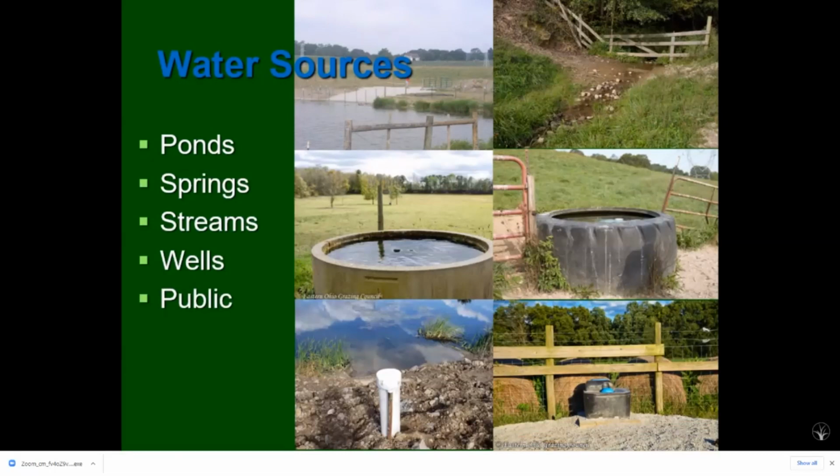Now we're going to get into water sources. And I'm going to spend some time here on each one of these because we're talking to a large area, and some areas of the state have more instances of these different water sources than others. But ponds, in my area of the state, we don't use ponds very often because the only ponds we really have are what was left over from the strip mining operations. Our soils just aren't conducive to building ponds and holding water.